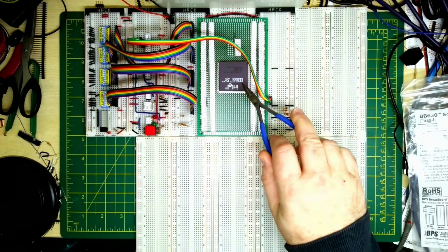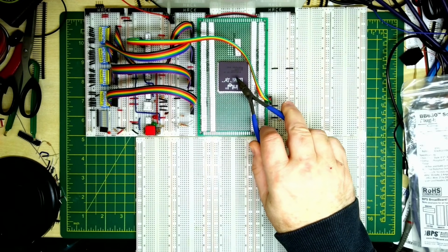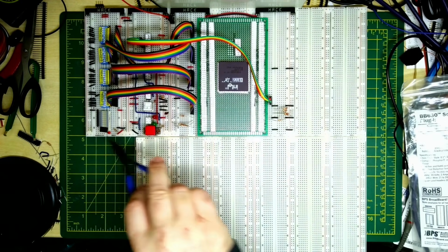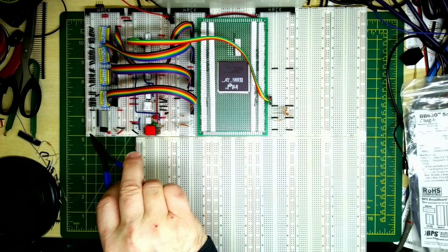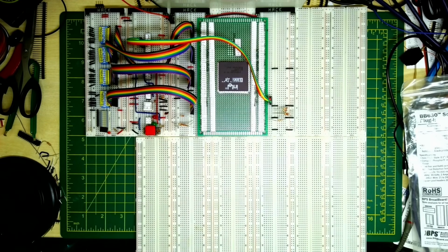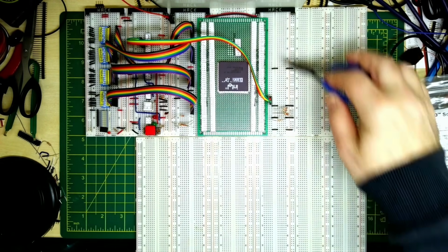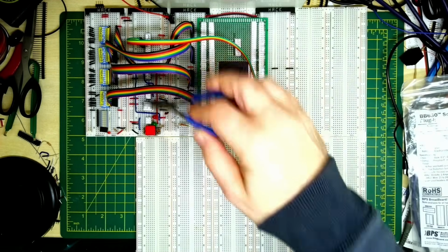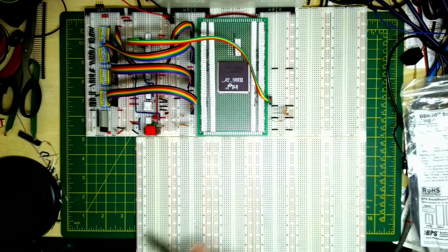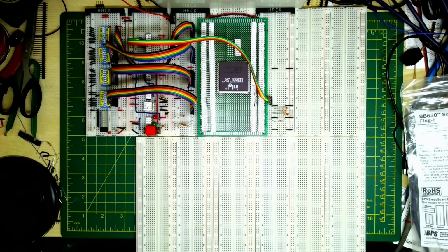So this is our breadboard adapter for our 386 processor. Some of the test boards, the clock and the test boards that I've got here, some of these will go. And what we're going to be looking at during this video is the schematic diagram to work out how to lay out all the components. We're going to be having a variety of latches and buffers at the top here, and a lot of the bus control logic is going to go down the bottom here.